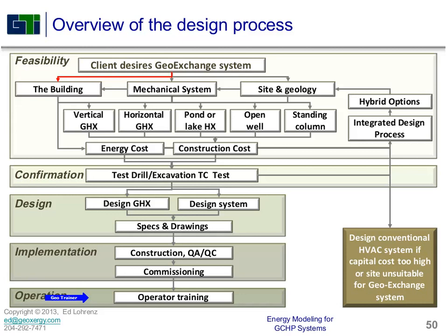It's not going to change the thermal conductivity of the ground. It's not going to change the amount of energy that you're trying to shove into the ground. The ground can only take so much energy, and putting in a bit more heat exchanger is going to get it into that mass of dirt a little more quickly than if you had just a single U-bend in there. But it's not going to change the amount of energy, the length of the ground loop, by a whole lot.